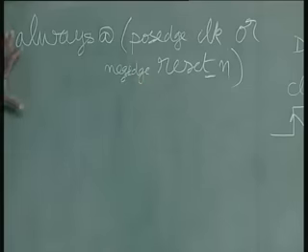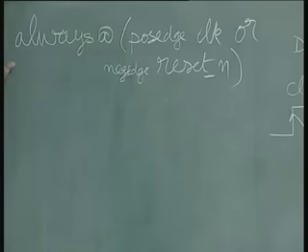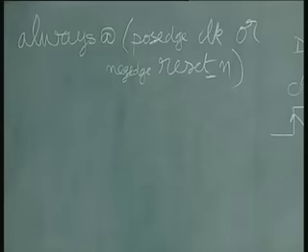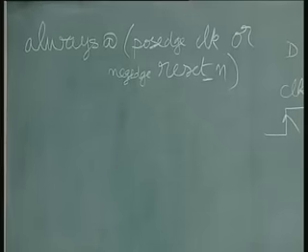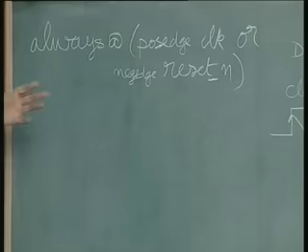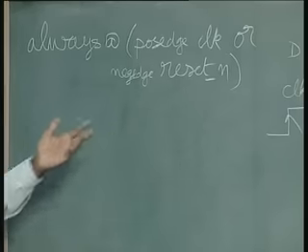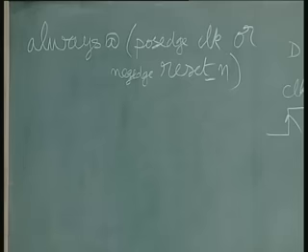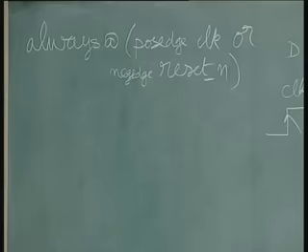Right. So in sequential realization, for a flip flop or register, another name usually encountered is a register instead of a flip flop. Hereafter we may be referring to a register as such, which simply means either a D flip flop or any other flip flops. Fundamentally, when you see a synthesis tool and finally get the circuit out of it for the code that you have written, you will be seeing only D flip flop in most of the places. In fact, almost all the places D flip flop will be used.